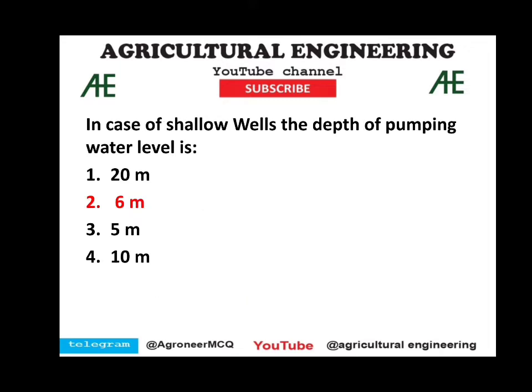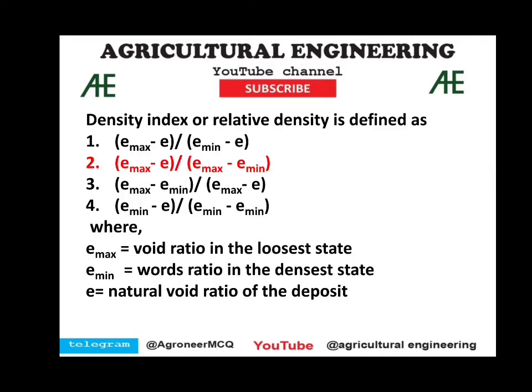In case of shallow wells, the depth of pumping water level is 6 meter. So you should know the depth of pumping water level in shallow water wells. Density index or relative density is defined as E maximum minus E divided by E maximum minus E minimum, where E max is equal to void ratio in the loosest state, E minimum is void ratio in the densest state, and E is equal to natural void ratio of the deposit. Void ratio is nothing but volume of voids divided by total volume.